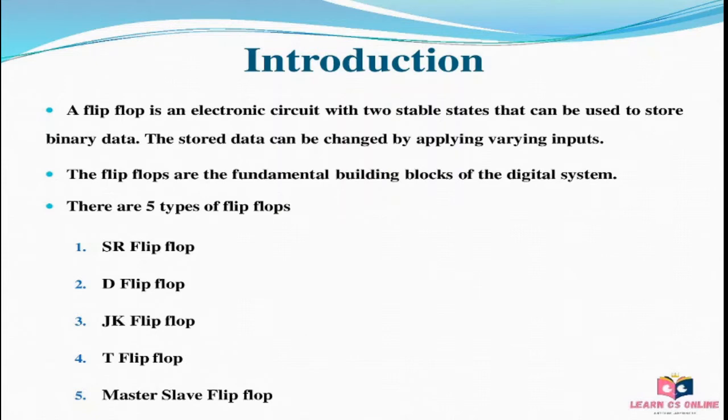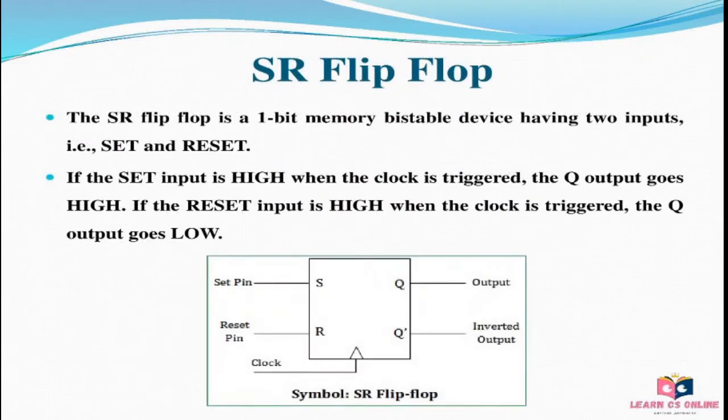Flip-flops are extensively used in counters, frequency dividers, shift registers, storage registers. There are 5 different types: SR flip-flop, D flip-flop, JK flip-flop, T flip-flop and master slave flip-flop. First type of flip-flop is SR flip-flop. The SR flip-flop is a 1-bit memory bistable device having 2 inputs, that is, set and reset.